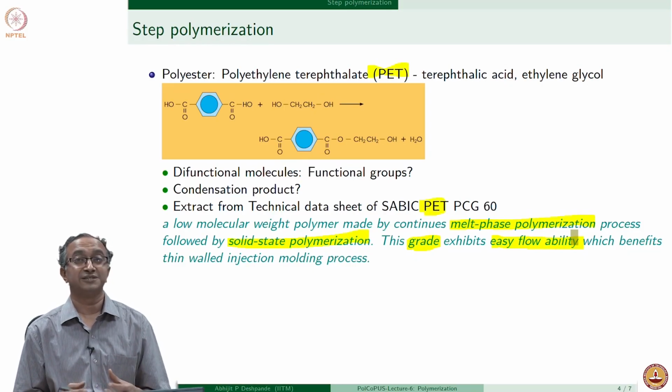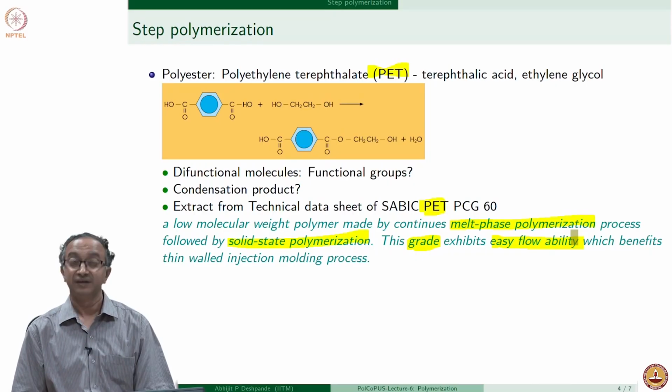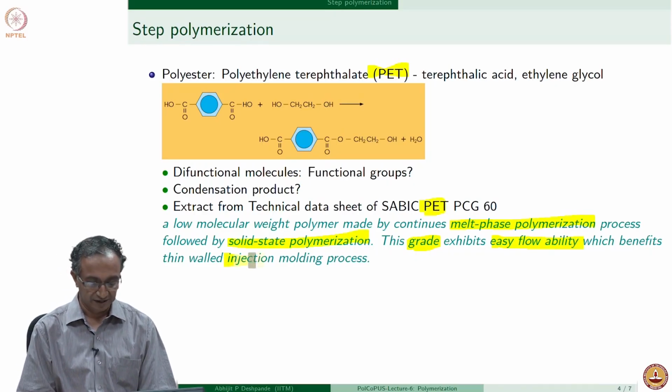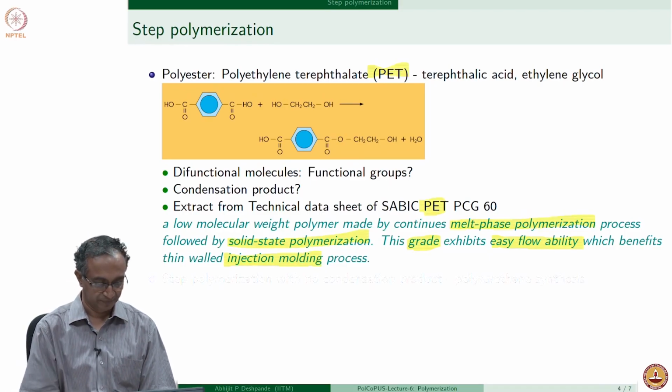So clearly in this case, by manipulation of polymerization techniques, they are able to get a target molar mass distribution which can ensure flowability and therefore good molding characteristics and of course appropriate mechanical properties for the eventual application.